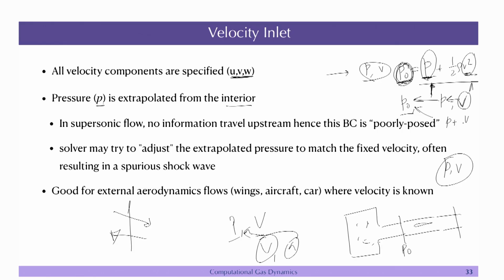So, let us say you fix the P and V both, right. So, now when you are trying to calculate these Riemann invariants or whatever value that is coming out, okay, there will be a mismatch, because one thing can get in, let us say velocity is getting in and pressure is coming out, okay. One is incoming and another is outgoing. So, in the combination of both, which can be the Riemann invariant, it can satisfy whatever is coming in and whatever is going out. If you specify both of these, one of them will not obey. So, either the characteristic will completely go in or it will completely go out. So, you can't have a combination of things, something going in, something going out, right.